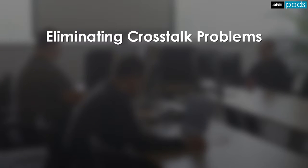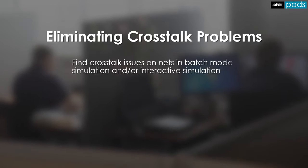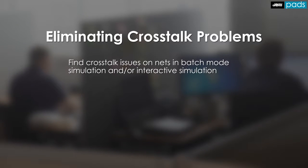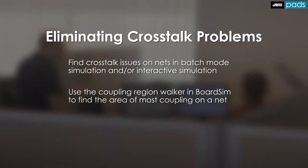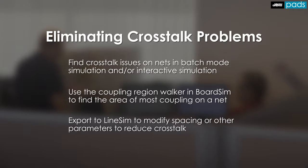Crosstalk problems on the PCB can be easily located and fixed using HyperLynx. After exporting your design from PCB layout, run simulations in batch mode and/or interactive mode to identify potential crosstalk issues. BoardSim's coupling region walker enables you to pinpoint exactly where the most coupled regions of a net are.